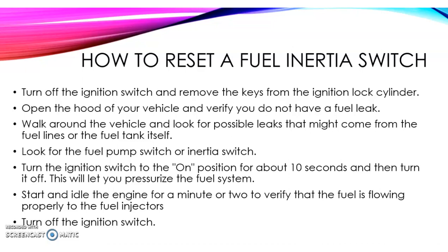Next, look for the fuel pump switch or inertial switch and turn the ignition switch to the on position for about 10 seconds and then turn it off. This will let you pressurize the fuel system. Next, start and idle the engine for a minute or two to verify the fuel flows properly to the fuel injector. And lastly, turn off the ignition switch.